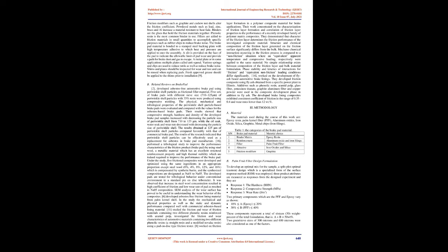A slit is provided on the face of the pad to indicate the allowable limit of pad wear and provide a path for brake dust and gas to escape. A metal plate, or in some applications multiple plates, called anti-squeal. Various springs and clips are used to reduce rattle as well as reduce brake noise. Shims and plates should be inspected for wear and rust and can be reused when replacing pads. Fresh approved grease should be applied to the shims prior to installation.